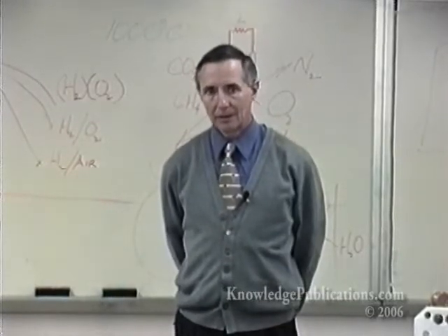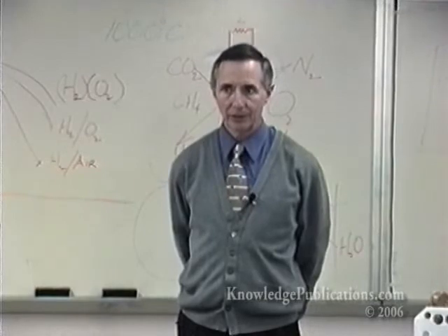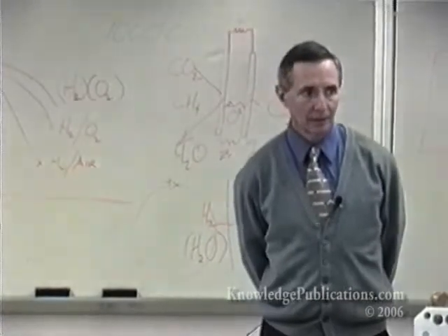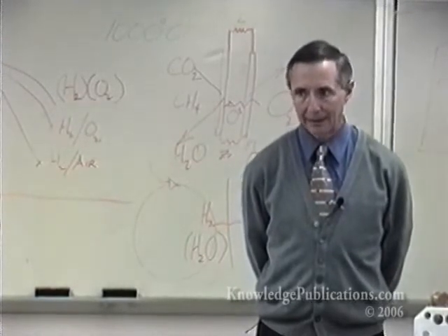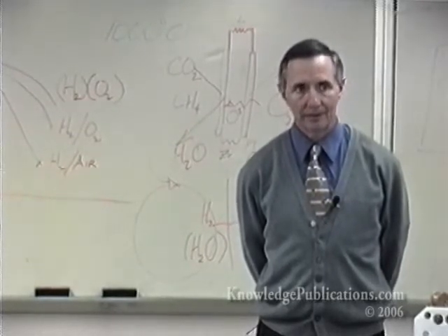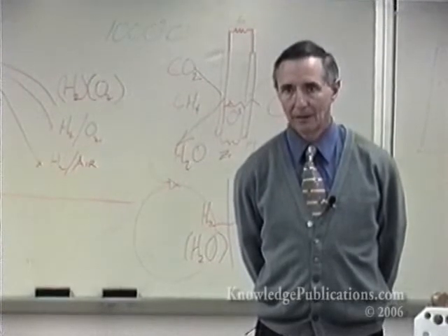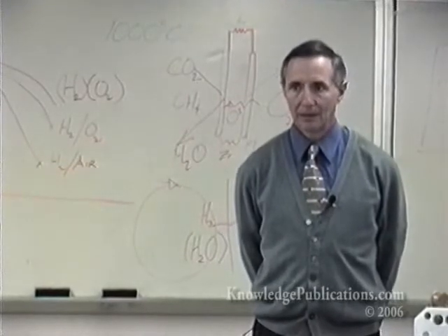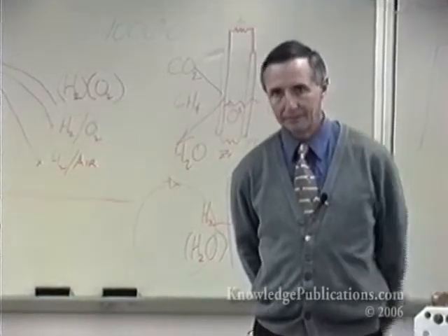The more you run it, the better, except if you're ingesting impurities either in the air or in the hydrogen stream that would poison it. The type of impurities that can poison this cell are oil. If you're using oil compressors and delivering to it a compressed supply of oil-laden air, it'll ruin it. Or if you have a supply of hydrogen that has oil in it for some reason, such as having been put through a compressor, that can ruin it. It ruins it by ruining the catalyst. This system is very sensitive to the functionality of the catalyst. If the catalysts are blinded, the platinum.